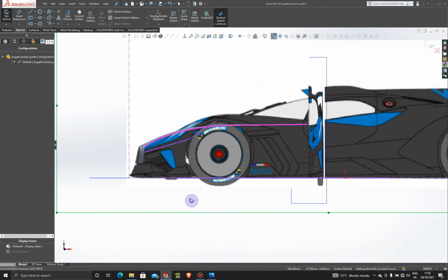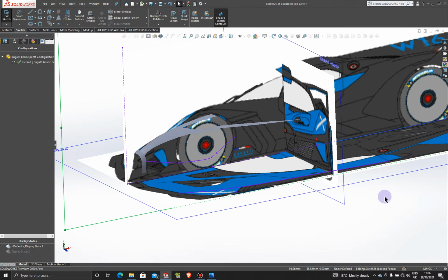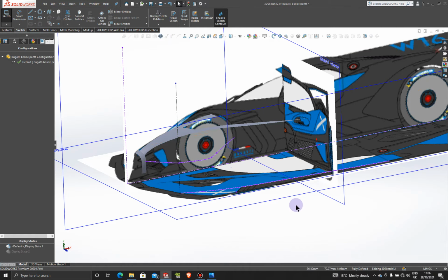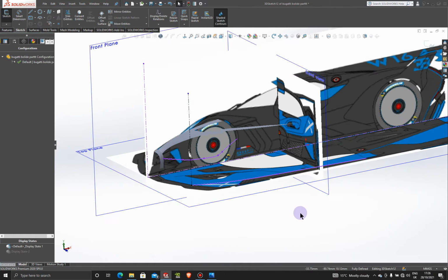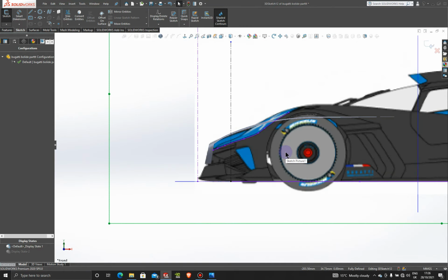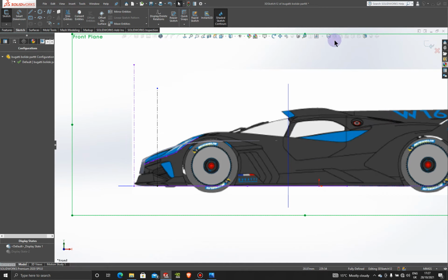So to do that, first we're going to build a scaffold line, construction line. So let's get into a 3D sketch and grab that center line and just bring that center line up from here. Of course, we want to be in Y and X or X and Y. All right. So that will give us a reference about where that point actually is, and it's right here. Okay, so now we can see things a lot better. So exit this 3D sketch.